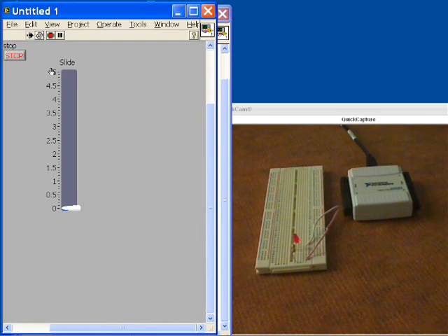So we'll go to the slider and we'll begin to move it up, and then you'll see as the voltage increases, we get a light intensity coming out of the LED at the level that's set by our slider. So as we go up and down, we see that we're changing that voltage value, and the light intensity changes from the LED. So this is a pretty straightforward application. I think you can see how to set it up. And this is how you do analog output with the USB 6009.